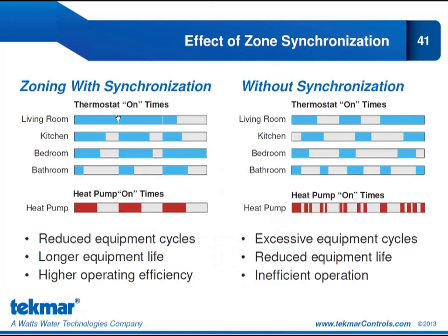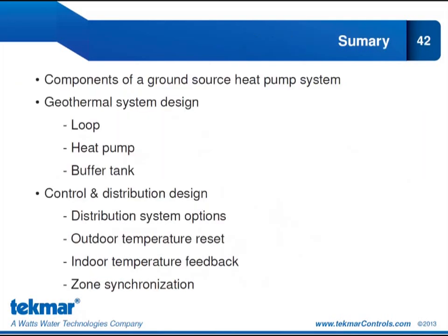Only when the cycle is complete can the zones call again. So all the zones are going to call for heat at the same time again, and likewise they're going to turn off as they become satisfied. The impact that has on the heat pump, you can see the on times are longer and there's no repeated on-off cycling. So we're going to have reduced cycles, longer equipment life, and the big one here is the higher operating efficiency.